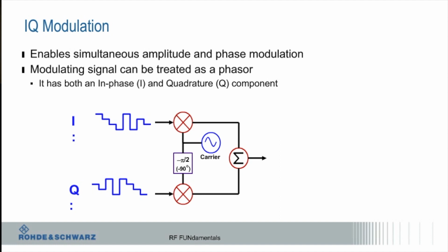The node at the top should be I. The node at the bottom is Q. They come out at the same frequency. If you look at the spectrum, you're going to see that carrier with some bandwidth associated with it. Again, we like these because they're easy and cheap.